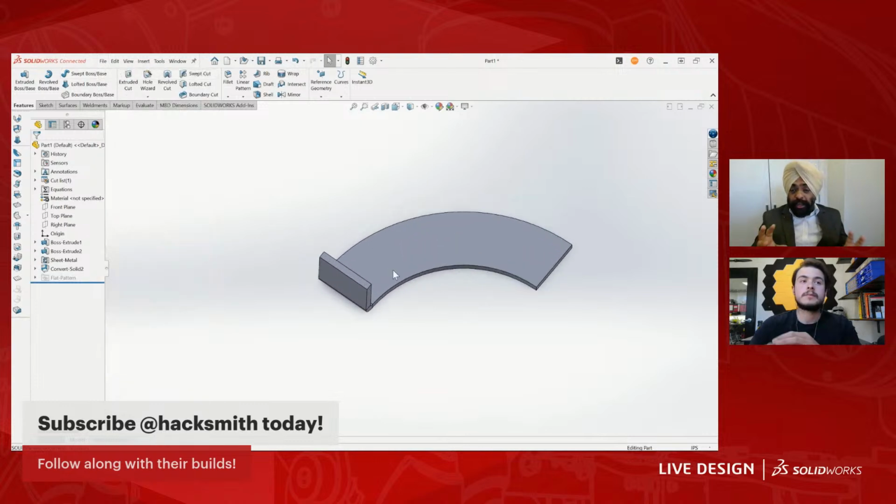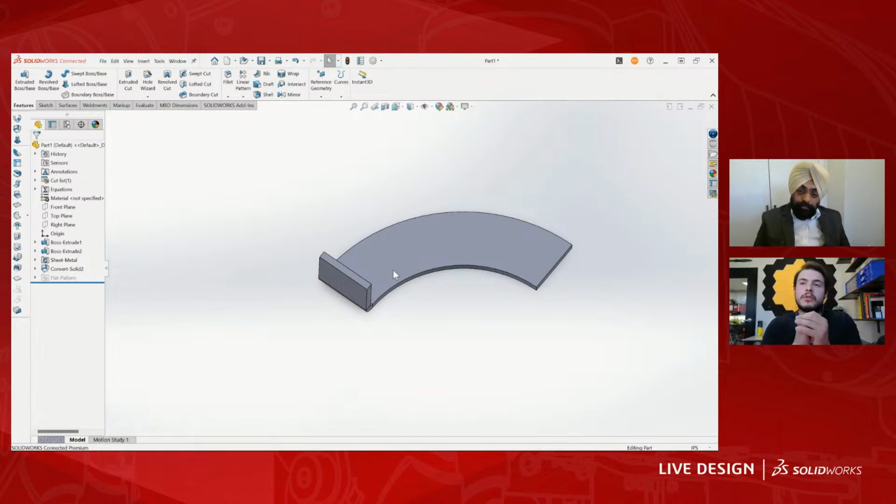So which way is better? I'm comfortable with both, but what's your advice to someone who is new to SolidWorks sheet metal? I've used both for a couple of different things. If there's a lot of complicated geometry, a lot of complicated bends that all need to line up, for example, we were making a half-scale Cybertruck based on the Tesla Cybertruck design, and that actually just generated the entire body initially with all the chamfers and all the cuts and all the angles, and then unfolded that into a flat pattern to be able to laser cut